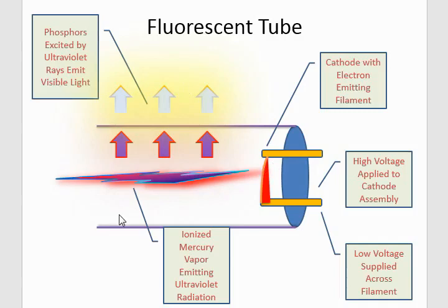When the mercury vapor is ionized, it largely produces ultraviolet light, which isn't any good. It's not what you're interested in. But the ultraviolet light excites phosphor on the inside of the tube's surface. The phosphor mixture then produces the visible light we want. Since the mercury vapor can tend to condense within the tube at room temperature and below, there are some special considerations with fluorescent lamps.